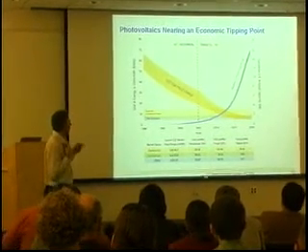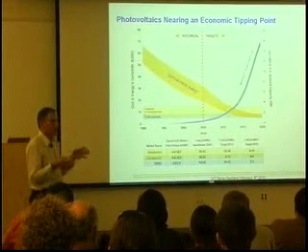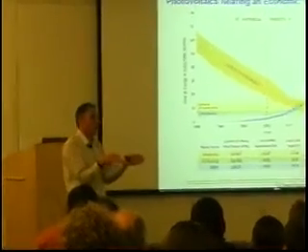The cost of a photovoltaic system is harder to calculate because usually what happens is you buy it as an investment and you use it for the lifetime, which is a warranted lifetime of 25 or 30 years, and you have to find the average cost per watt of the energy generated over that lifetime and so forth. But when you do that calculation, all of those same features are incorporated: depreciation, service, reliability, and so forth in both. So I think this is a fair comparison.